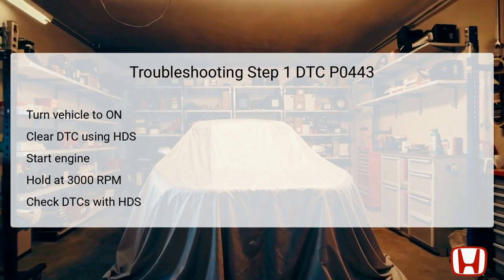If the code reappears, it confirms that a fault is indeed present, and you can move to the next steps in the troubleshooting process. Conversely, if the code is not present, it may indicate an intermittent issue that warrants further investigation of the system's wiring or connectors.